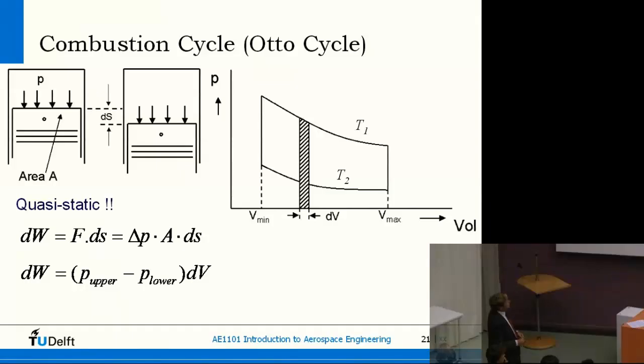Well, if we do this, you can say that this is the amount of work being done by the engine at high temperature when it expands, and this is the amount of work being done when compressing the air. And the trick is, of course, the temperature difference. So when you expand at a higher temperature than what you compress, you get a net difference of work, and this means that the area of this PV diagram, this enclosed area, is basically the amount of work that the engine performs in 1 stroke. So if you know the strokes per minute, then you can also count the power.